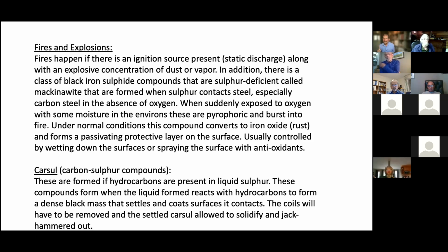Another interesting thing is you do not sweep sulfur tanks. Typically, you do not sweep sulfur tanks with nitrogen because that allows these compounds to form. And then during maintenance shutdown periods, you can't help it. You shut off the nitrogen, oxygen comes in, and you catch fires. So typically, liquid sulfur tanks are swept with air.